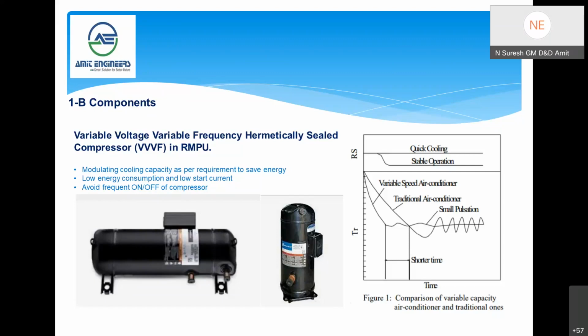In the horizontal compressor, there is an additional small inbuilt oil pump, since it is horizontal, to have proper lubrication to the mechanism. Whereas in the vertical one, oil lubrication happens due to centrifugal force. Both are oil compressors. There is no oil-free compressor.